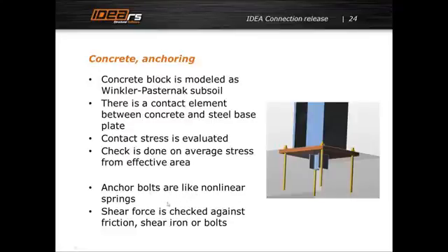Anchor bolts are again like bolts, like we spoke a couple of minutes ago, and we check also shear force, and this shear force in our model can be taken only by friction, or by shear iron like here, or by flexure stiffness of these anchors. We are also able to take into account the mortar joint.